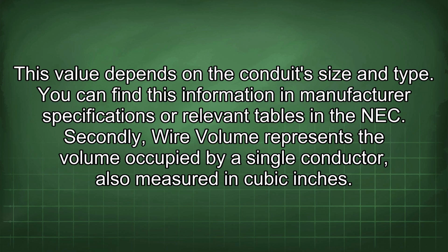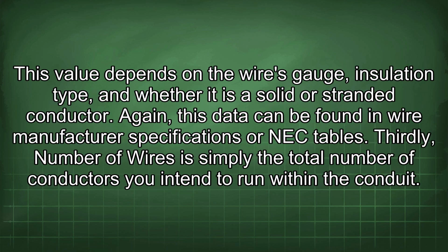Secondly, wire volume represents the volume occupied by a single conductor, also measured in cubic inches. This value depends on the wire's gauge, insulation type, and whether it is a solid or stranded conductor. Again, this data can be found in wire manufacturer specifications or NEC tables.